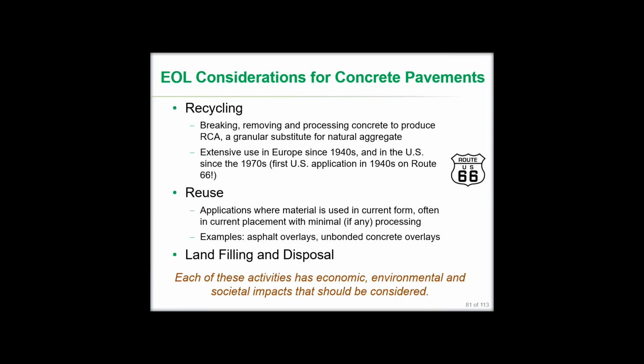And finally, and I'm working backwards up the list as you've probably noticed, recycling, the process of breaking up the existing pavement, removing it, and processing it to produce recycled concrete aggregate, or RCA, which we're then using as a substitute for natural aggregate, virgin materials. This is a process which has been around for a long time, more than 70 years, going back to relatively extensive use in Europe in the 1940s, after World War II, and even in the United States, a little bit building on the European experience.